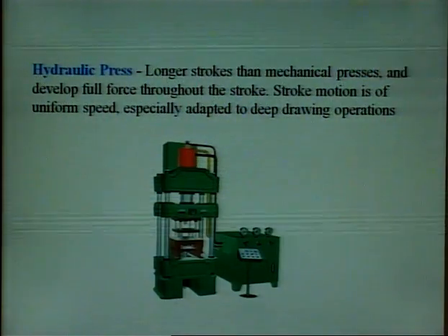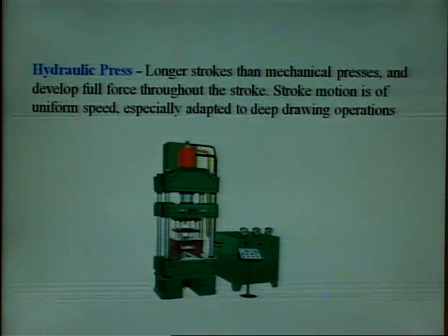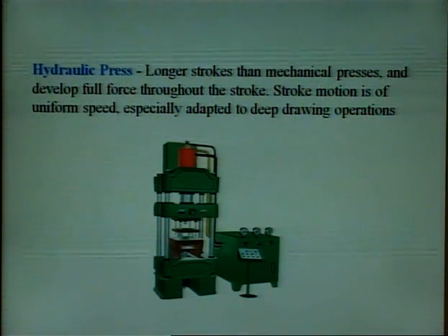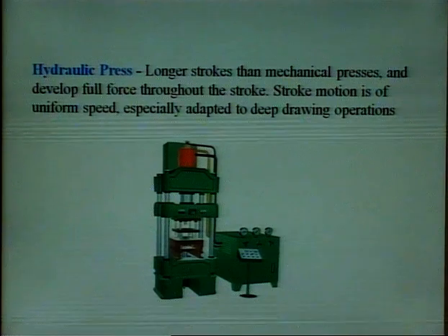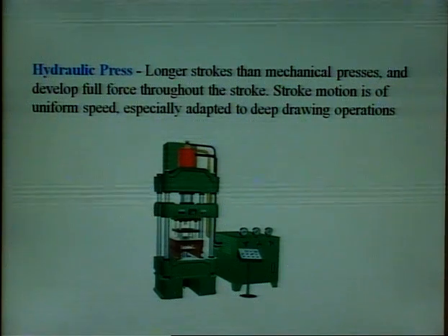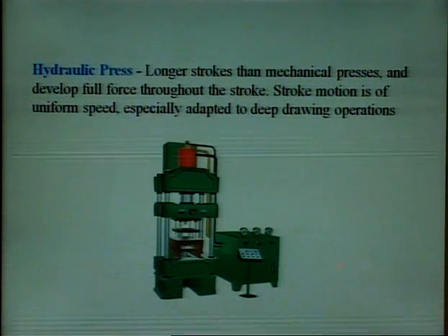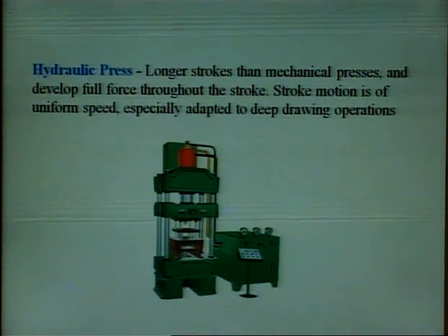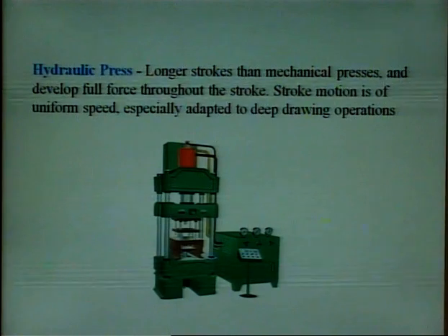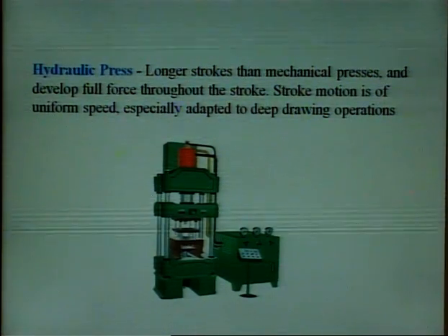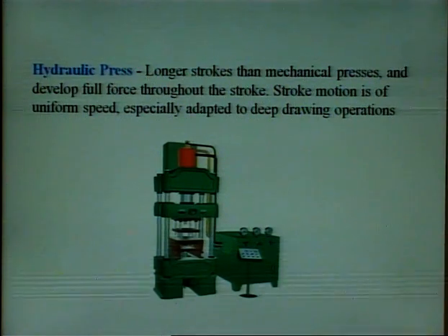You can have a hydraulic press also here. Hydraulic presses can have longer strokes than mechanical. Forces can be higher, and the stroke motion is uniform, of uniform speed, because you are providing it through a hydraulic media.